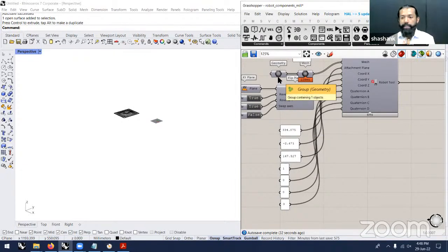So you can either add the exact model with the complete accurate measurements of the space and the tool, or you can feed in the tool center point and the work object location and just give it a movement plan, so that it will still look at the actual figures within the actual coordinates of the object and the tool and mill the path.